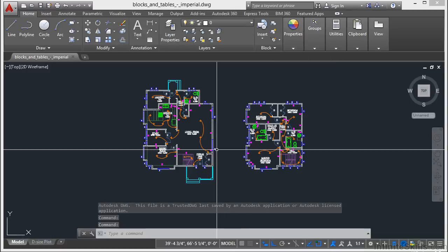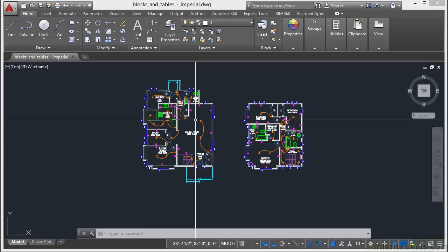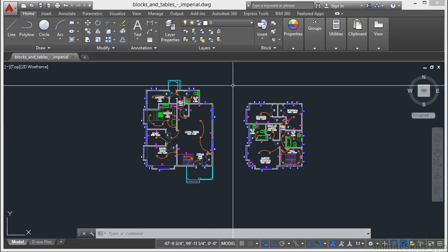This is a great file to look at Osnaps because there are a lot of different object types in here that we can snap to. Osnaps make sure you place your objects in a very specific place on a specific object. Now, you can enter an Osnap by typing an alias on the command line, or you can access them through a shortcut menu, or you can utilize what's called running Osnaps. Running Osnaps keep the Osnaps on all of the time.